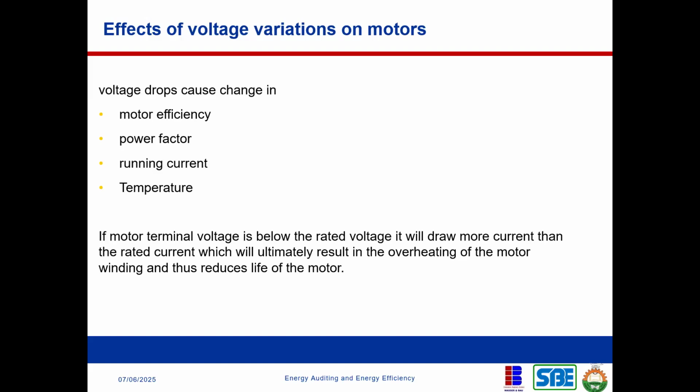So if the motor terminal voltage is below the rated voltage, as I've just explained, it will draw more current than the rated current, which will ultimately result in overheating of the motor.